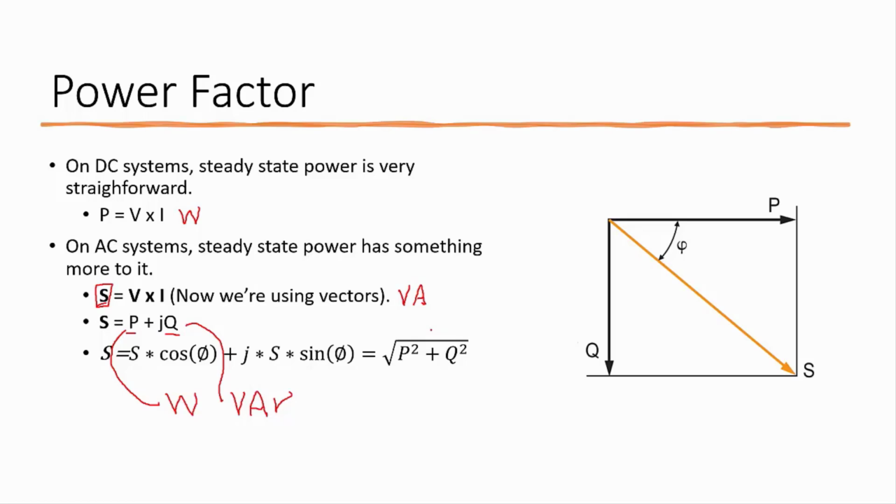But there is a very simple analogy which you may have seen 1,000 times to explain what power factor is. Now, the relationship between these three quantities is very important because apparent power is the full power that we're using on the system. And that power can be divided into active power and reactive power. And of course, the proportions of every single element can be quite different, and they will turn into very different system usage. Now, you may notice that there is an angle here called phi, the power angle, that is the relationship between P and S.